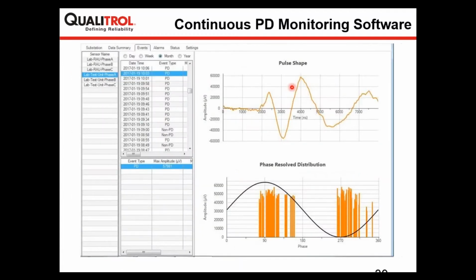For each of the recordings, you can see the detailed categories. The best case, or the beauty, of this software or monitoring system is that whenever it performs a recording, it categorizes every recording. So here in this recording you have only one type of category. If there is different partial discharge activity or different noise signals, these will be categorized separately. So you just need to click on each of the categories.